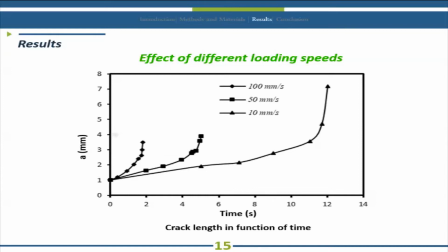The ABS approaches a completely fragile behavior at high speeds. Indeed, when the loading speed is high, the surfaces of the crazes quickly move away, which justifies the sudden rupture of the ABS. The macromolecular chains do not have enough time to reorient themselves within the crazes. Thus, the fibrils bridging the many cracks break because of the microvoids that are born around the defect, which results in a decrease of the tenacity of the ABS.